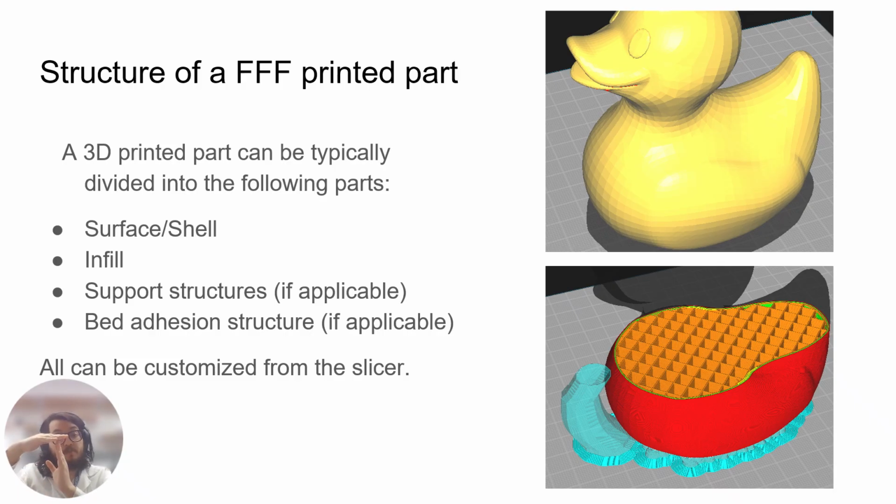So if you have something to print on top of, for example, a support structure that's being printed with the rubber ducky, then you have a higher quality sample. Sometimes you cannot print it without support structures. But they are not part of your sample. You're going to have to break them away. You're going to remove them, and those are, as I mentioned, if applicable, also printed alongside our structure.